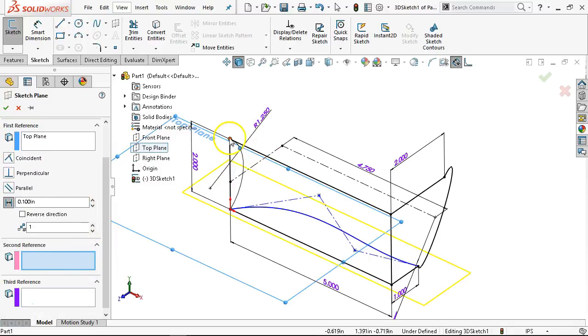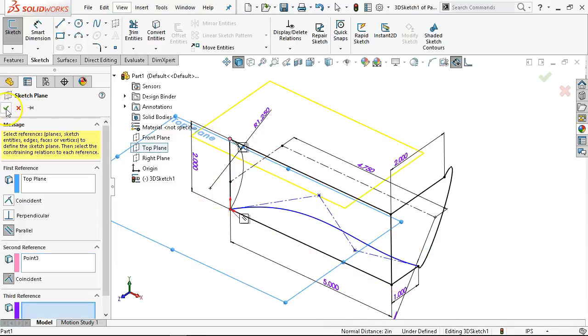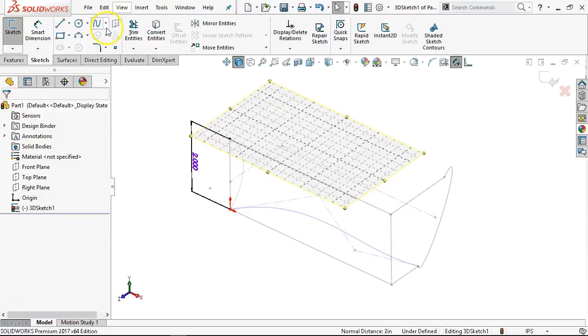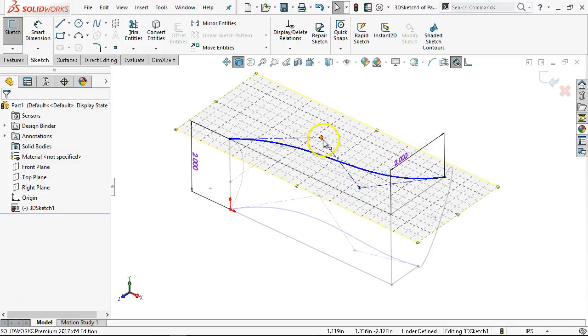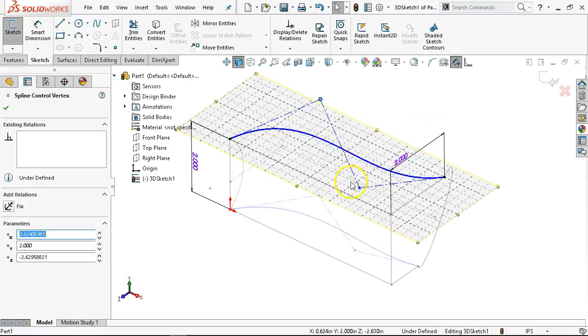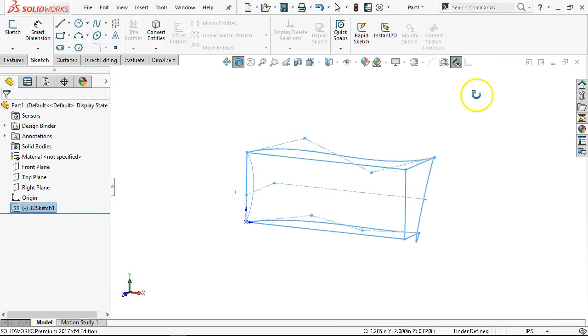Location at the second reference we'll put at the top of the sketch, and that's going to give me kind of the same thing. I don't want to end up with points going up and down along that wave if I don't need them. For this one, I'm not ready to generate that geometry, so we'll give this the same number of points. We can pull and push, and we'll put a little bit more into that one. See what it looks like.